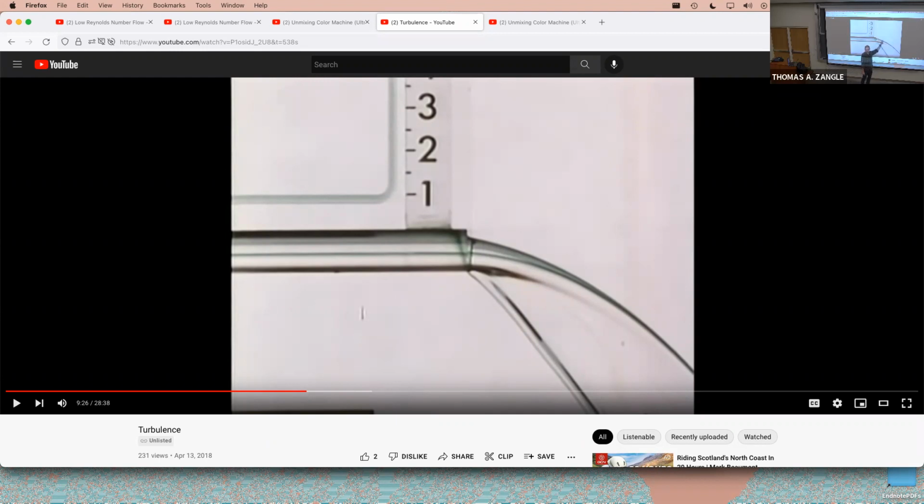We can actually understand this now if we know the velocity profile, right? The velocity profile is parabolic. So the flow in the center of the pipe is traveling faster than the flow at the edges. That fluid at the center has higher momentum than the fluid near the walls, where there's the no-slip condition. And therefore that fluid with higher momentum travels further out from the center of the pipe than the fluid at the walls. The fluid at the walls is slower, so it falls faster. You can actually see something about the velocity profile by looking at the outlet of the pipe.